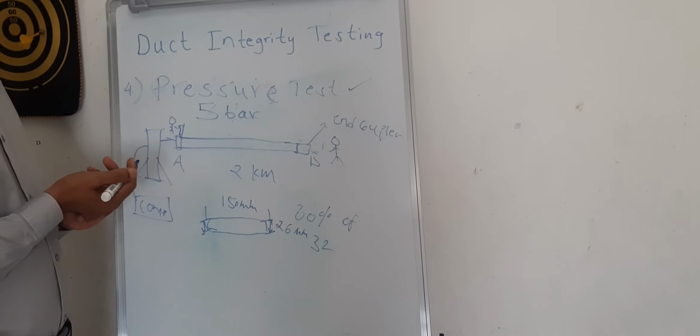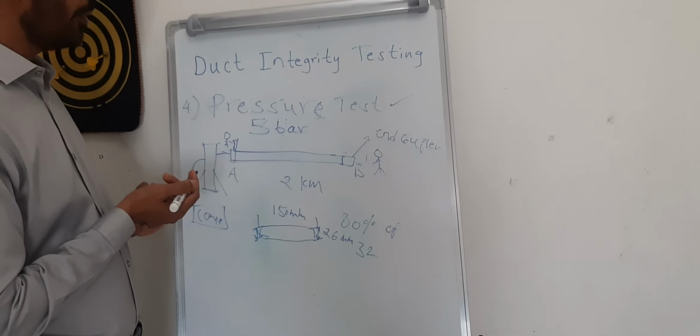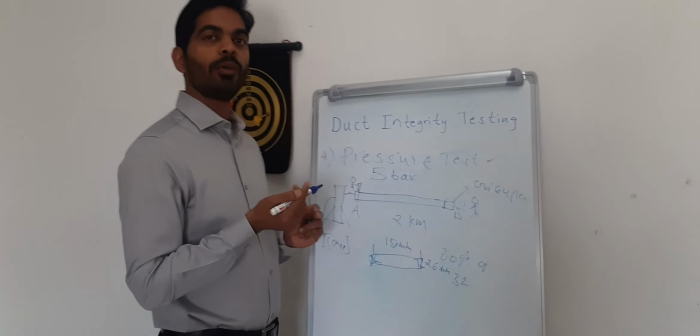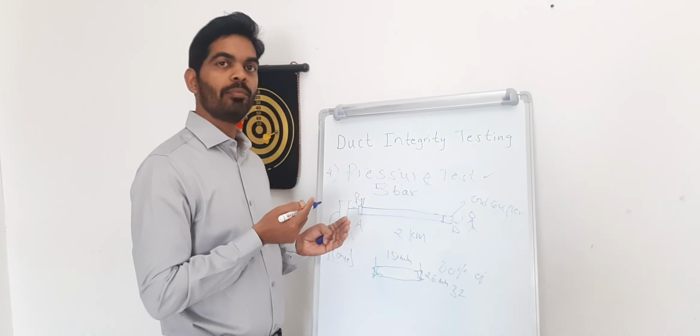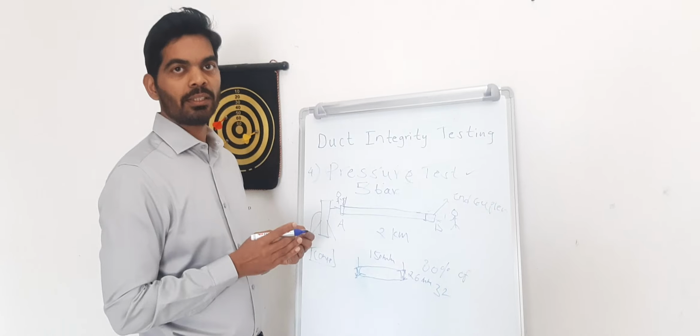You wait for 30 minutes. And in 30 minutes if the drop is less than 0.5 bar, that means your pressure test is passed.